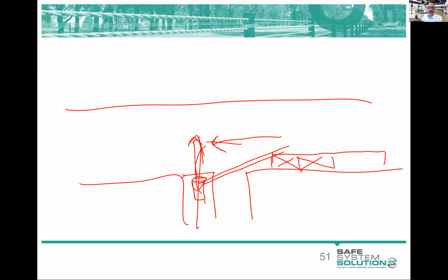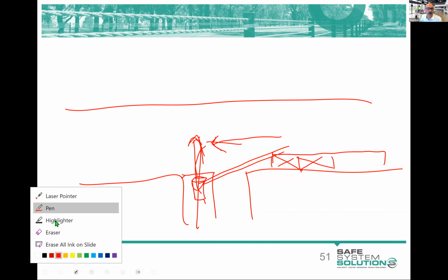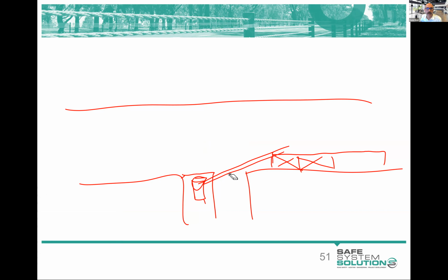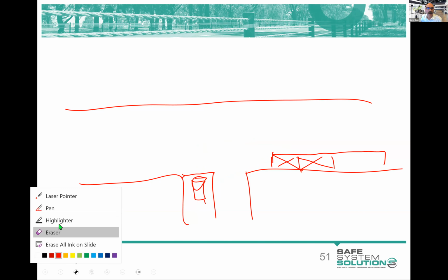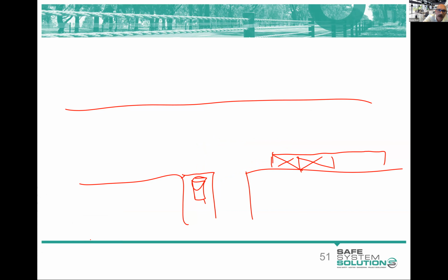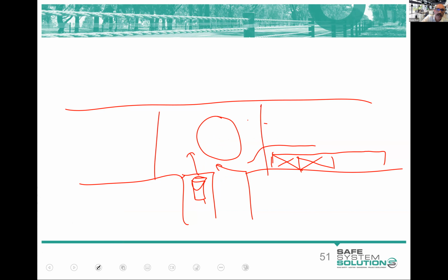So examples of primary treatments would be things like a roundabout, because we know that slows down this vehicle, and that crash type doesn't happen at the speed and severity to cause death and serious injury, passenger vehicle to passenger vehicle. It could be raising this intersection, for example. That would be a primary treatment, assuming you can get speeds down.